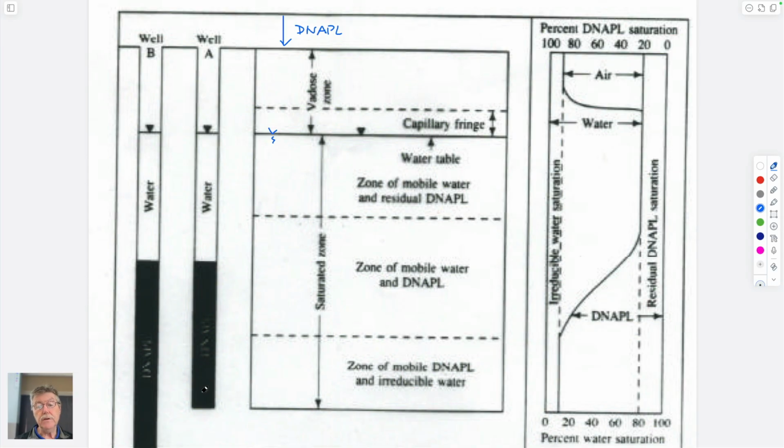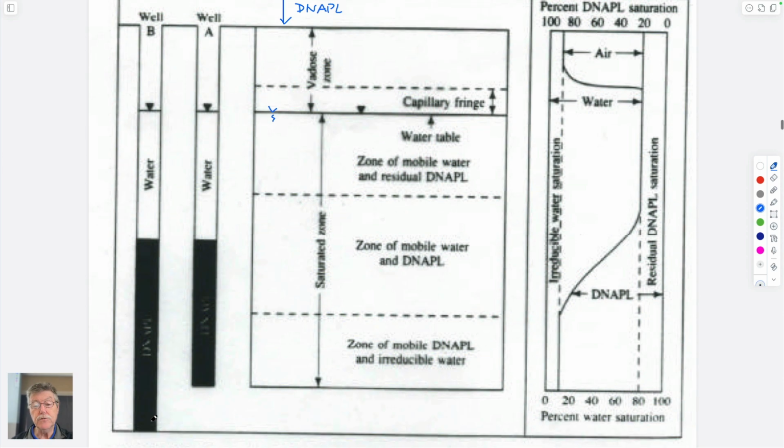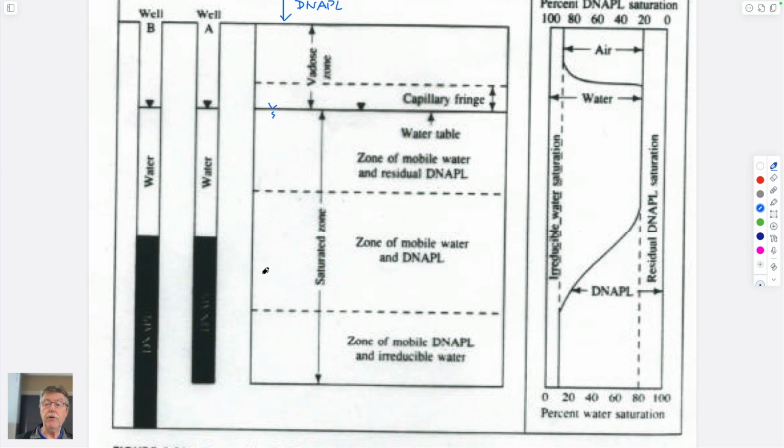So if you drill a well bore down to some depth, the height to which it rises is controlled by its behavior within the saturated zone, I guess. If you deepen that well bore, it will record a depth which is as deep as you want to drill the well bore, so long as there's enough volume of product that can come in to fill the well bore up to that particular depth. So here, the level of the well bore is here, the same in both cases. If you're taking this to be the depth of the material in situ, and there's a capillary barrier that sits here, even though the well bore is recording that here, that's not going to be a true depth. So I guess you have to be aware of that.